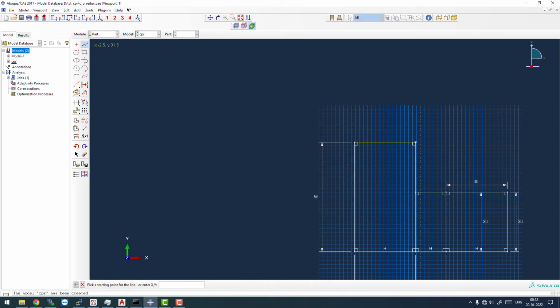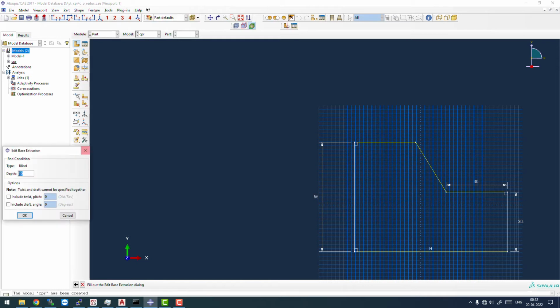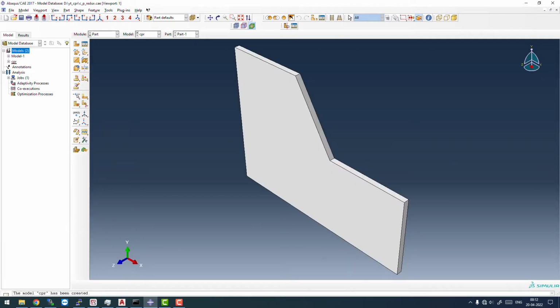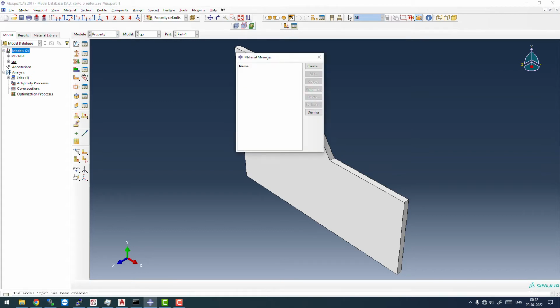Now we'll join them and create the slope. This is the slope. Now we'll remove the internal dimensions, which are these ones, in this. Now we'll join the bottom line, so as to not have any connections between the continuous line segments. Now I'll click on done. The depth we can keep up to about 2 meter, so we'll go with the 2 meter depth. This looks fine.